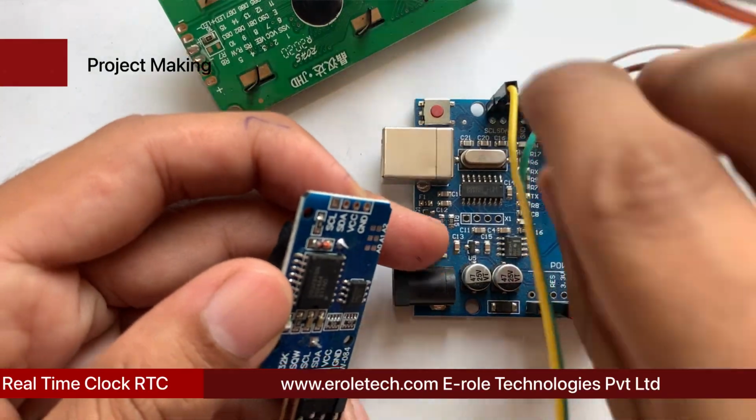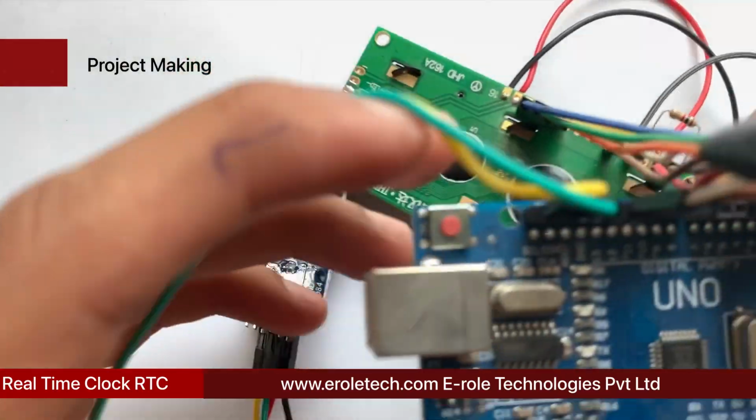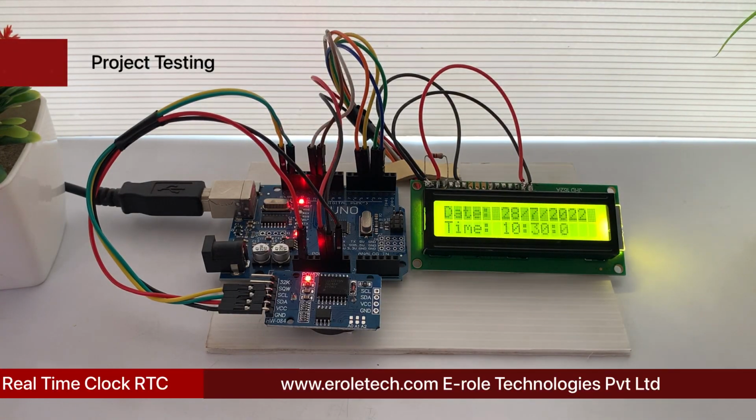Connect the yellow wire with SCL pin and green wire with the SDA pin of Arduino. Now we will power up our circuit and test its functionality. We can see that the RTC is showing the date and time on the LCD display.